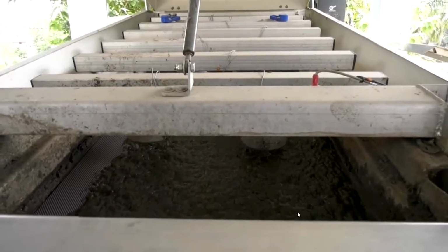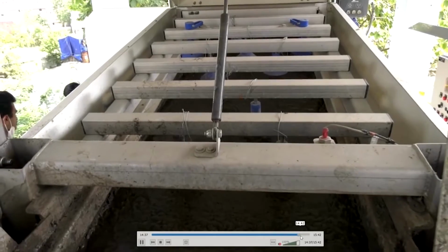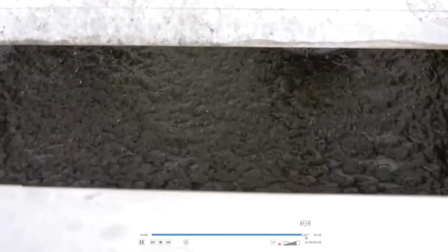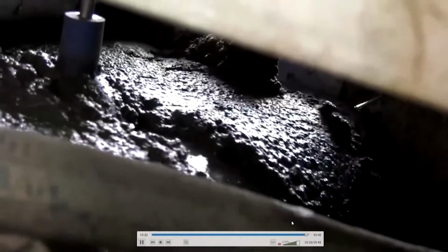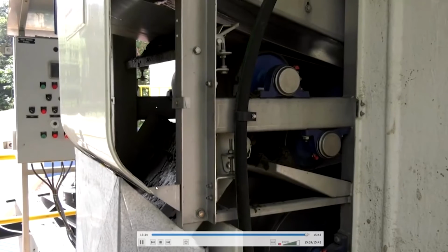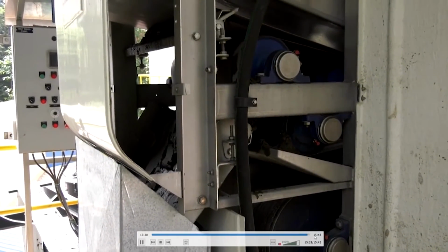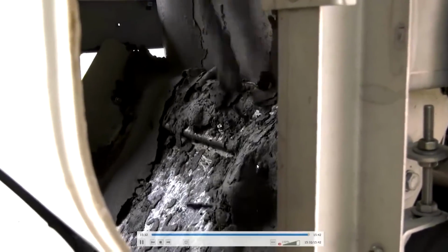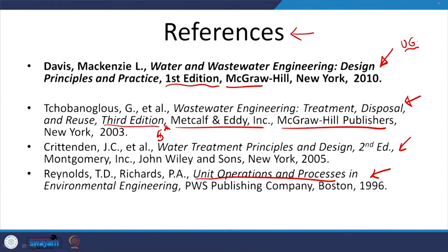So, that is why they are adding a polyelectrolyte, right, to form flocks, and we can see this sludge coming in. Sludge that is collected from the bottom. You have a filter press out here, and the sludge, dewatered sludge, as you see, is falling down from out here, right. Yes, this is the dewatered sludge that is composted typically. So, that is enough for now. We will look at this in greater detail later on. So, let us come back to where we were.